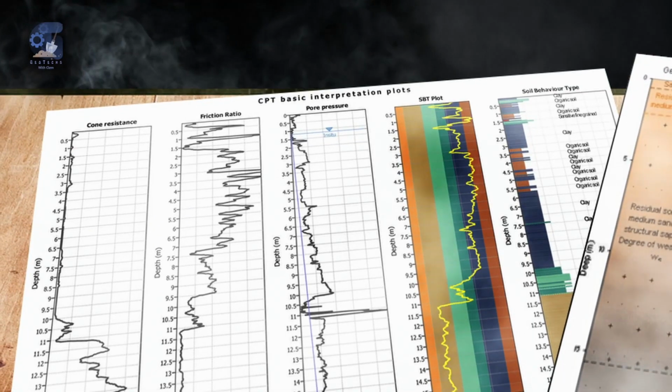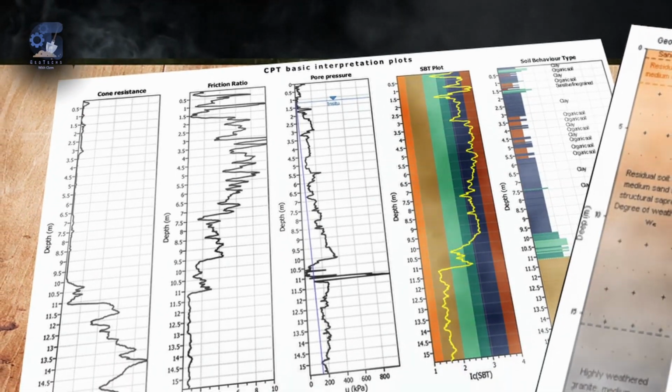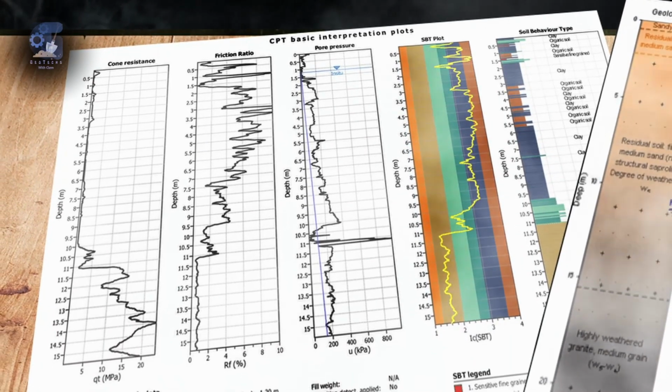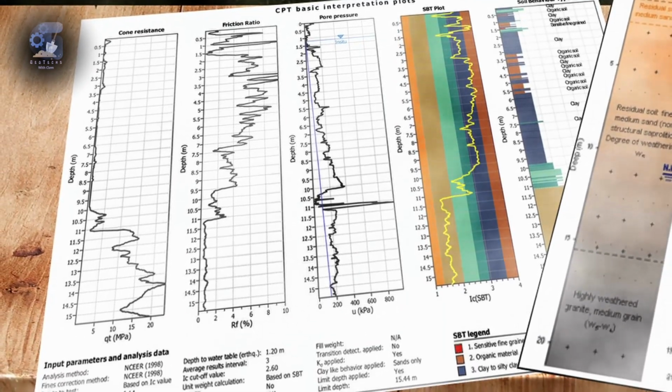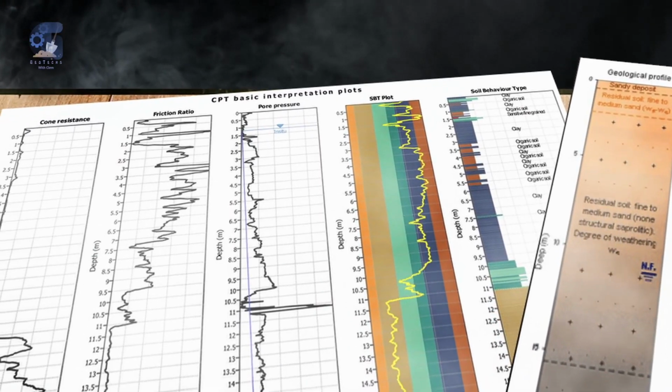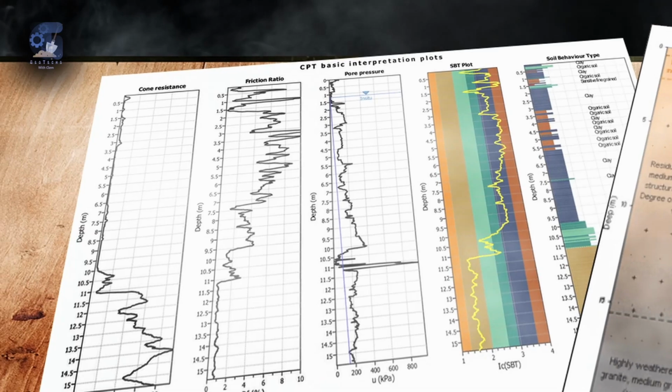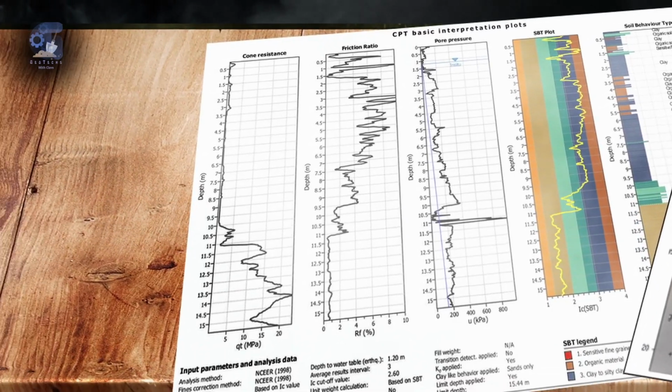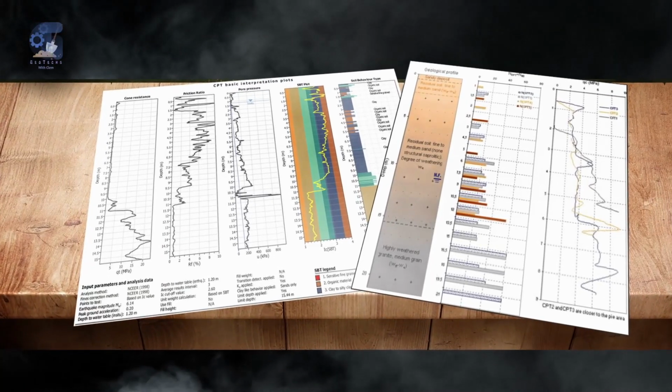Some of these instruments measure similar properties, but some are better than others depending on the soil conditions. For example, the cone penetration test has the advantage of continuously collecting information on the properties of the soil. It is therefore more accurate in determining soil profile when compared with the standard penetration test.